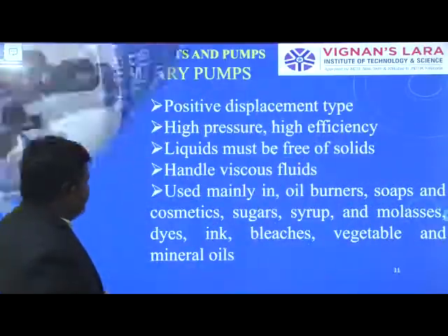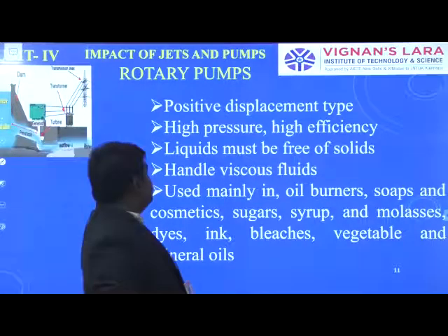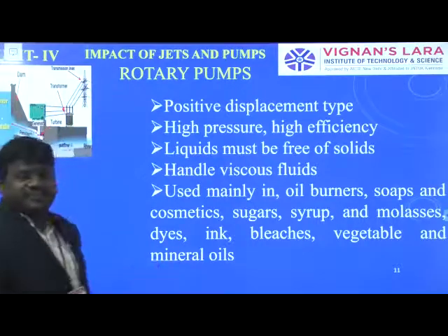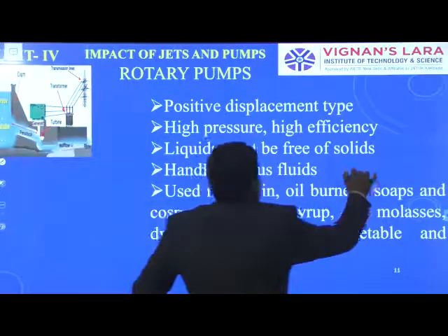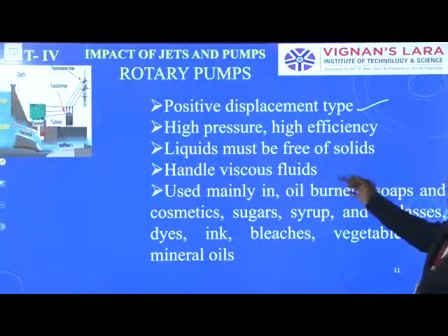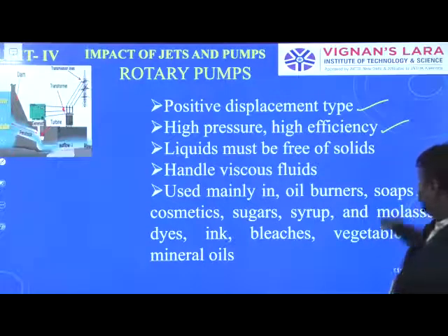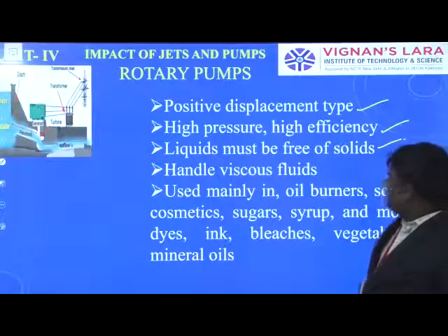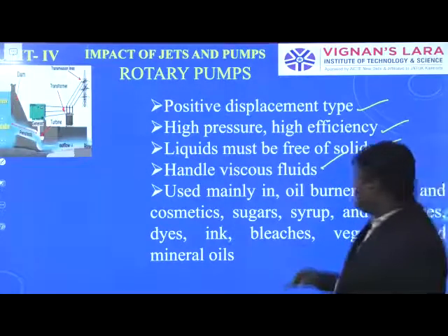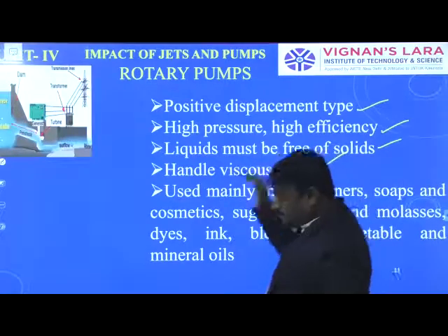pumps. And coming to the rotary pumps, that is a positive displacement type, high pressure, high efficiency. Liquids must be free of solids, and it can handle viscous fluid, and is used mainly in oil burners. So it is used mainly in this type of rotary pumps.